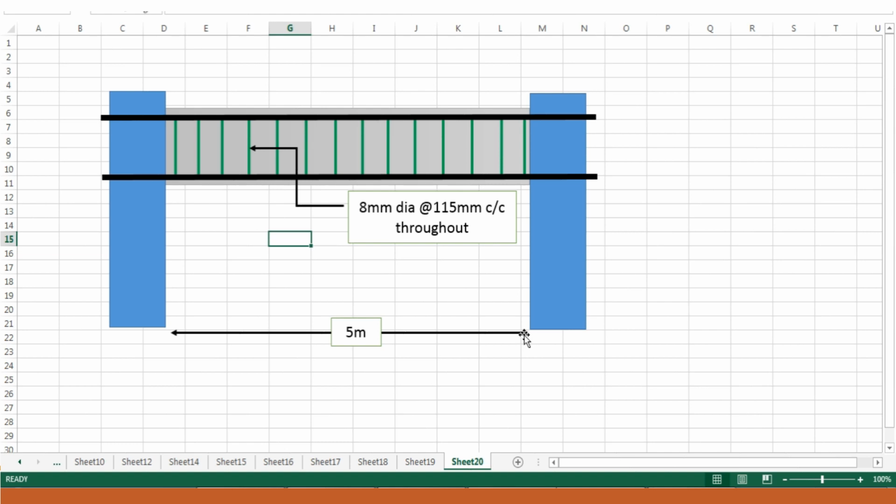So in this lecture, what we have done is that we have designed a beam for flexural forces as well as for shear forces. So we have detailed the beam as per IS 13920 for ductile detailing and for strength design from IS 456, such that we have provided the longitudinal bars as well as the spacing of the transverse reinforcement, taking into account the special confining zone at the ends as well, although there is no difference here between the central portion as well.